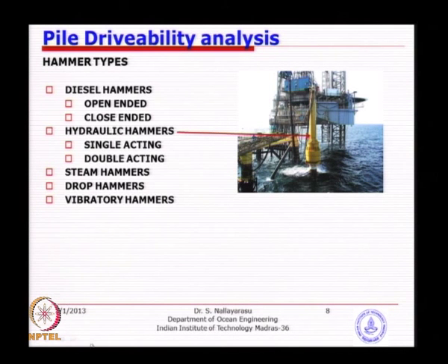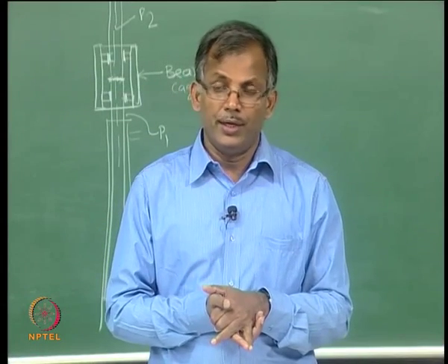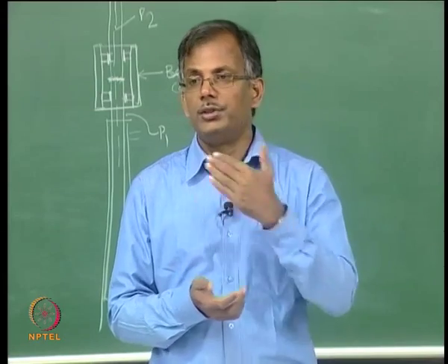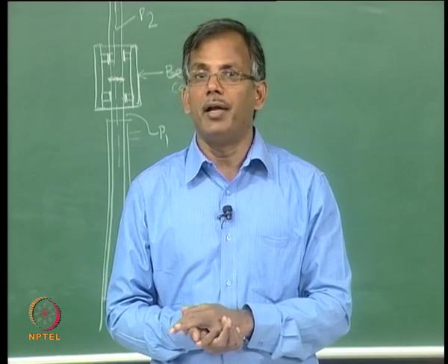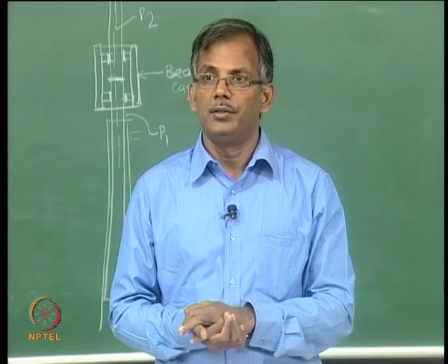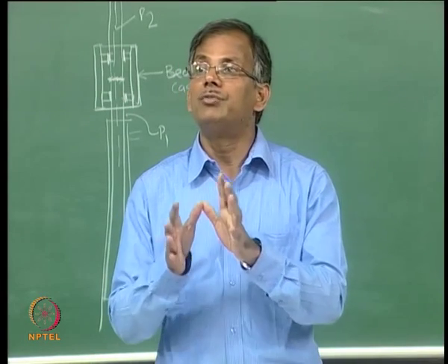I think most of the time for offshore applications we use hydraulic hammer for several reasons. It's easy to handle, number one, compact in size, and efficiency is very good. Comparing diesel engine or steam engine, efficiency is very, very high. In fact, sometimes we go to 0.95 as the efficiency, and breakdown is very, very less.